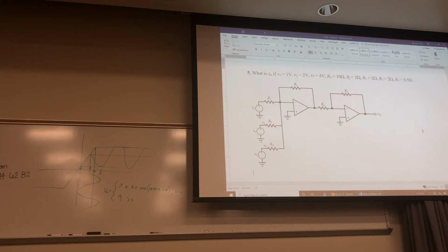Now, hopefully, when you see something like this, you can immediately jump to what the gain is, right? Hopefully you've seen this enough times. Just because if you have to do KCL every single time, it's going to slow you down. So it's really good to be able to recognize something like this and say, oh, I know what that is. That's an inverting amplifier, and I know what the gain is just based on the feedback and input resistance. Same here, another inverting gain type of scenario.